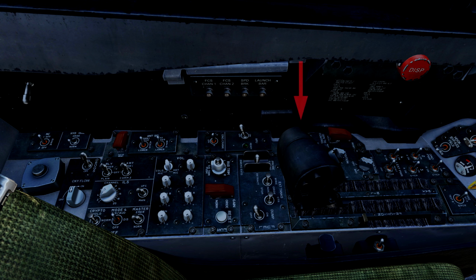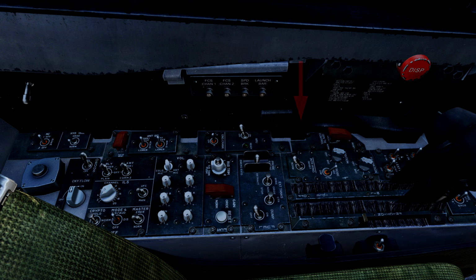And next we have the throttles, and the throttles are one half of the HOTAS system, and they provide hands-on control for functions such as the communications, the countermeasures, the speed brake, antenna elevation, and others. It's a split linear movement throttle, and it controls the thrust of both engines, but they're generally moved as a single unit, except during startup and shutdown. And the throttles do have automatic throttle control, or ATC, for both cruise and approach modes.